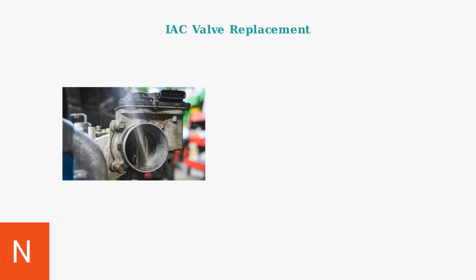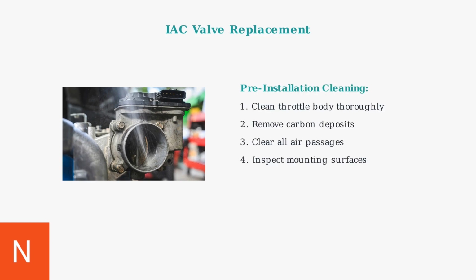Start by cleaning the throttle body to remove carbon deposits before installing the new IAC valve. Clean the throttle body thoroughly with appropriate cleaner. Remove carbon buildup from all surfaces and ensure all passages are clear before proceeding with the installation.